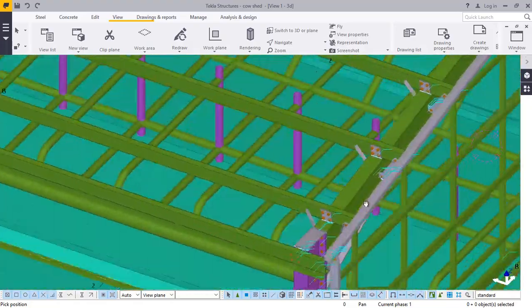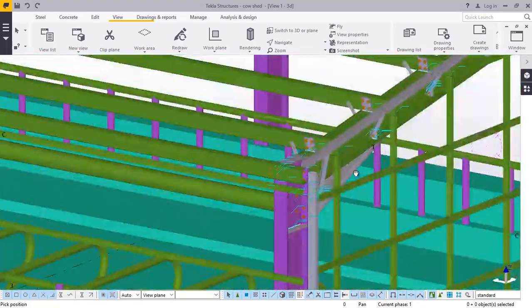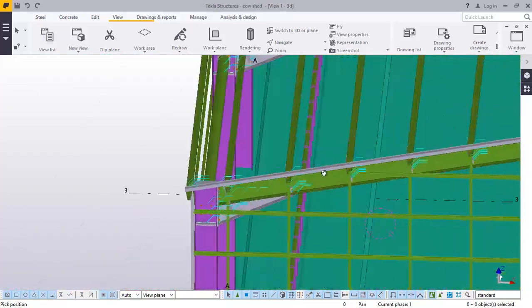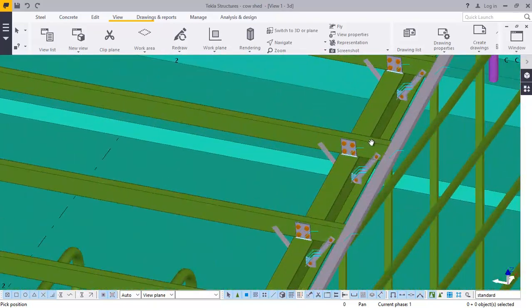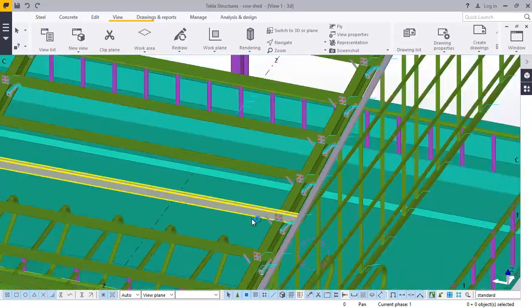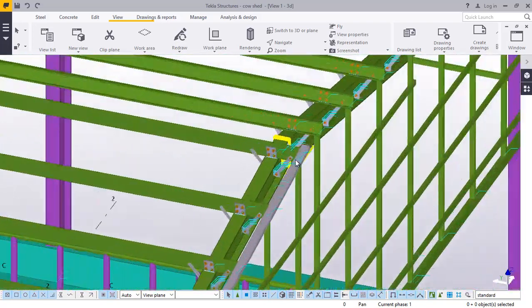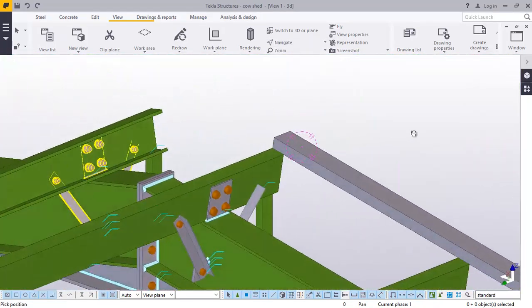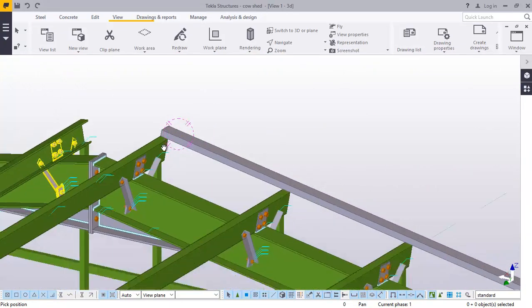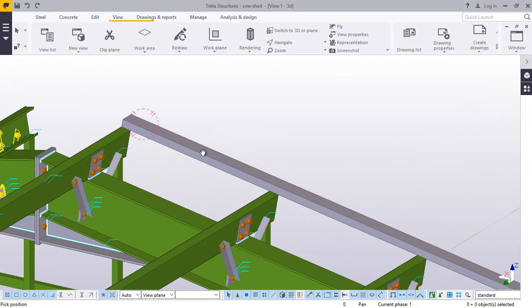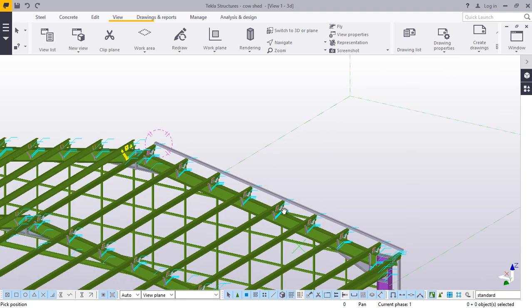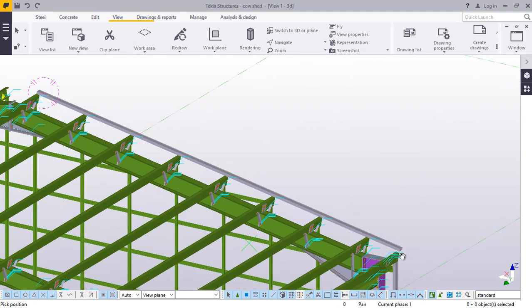Now, prior to doing anything, the gable is a bit tricky. On the gable, you'll be required to place a metal bar or any kind of a bar or a steel profile, taking the slope on top of the purlins up to the very last purlin.